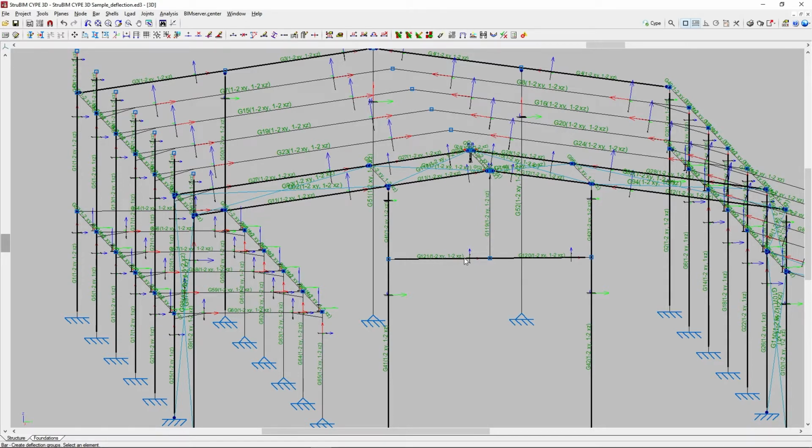By default, each individual bar itself constitutes a group of secant deflections. If desired, several aligned bars can be grouped together for the joint analysis of the deflection. To do this, we left-click on the initial node and then on the final node of the group of aligned bars.